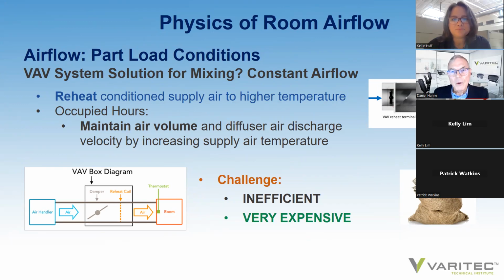Yes. Well, in the United States, ASHRAE Standard 170 is the standard that's used for healthcare design, and it assigns air change rates to patient rooms, which I think is at 6 air changes per hour, 12 air changes at airborne infectious rooms, protective environments are at 12 air changes, and operating rooms per the standard is 20 air changes.